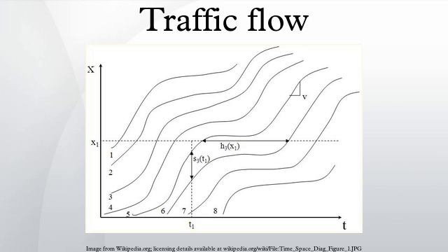Laval 2009 presents a framework for estimating analytical expressions for the capacity reductions caused by a subset of vehicles forced to slow down at horizontal-vertical curves on a multi-lane freeway. In each lane, the underperforming stream is described in terms of its desired speed distribution and is modeled as per Newell's kinematic wave theory for moving bottlenecks. Lane changing in the presence of trucks can lead to a positive or negative impact on capacity. If the target lane is empty, then the lane changing increases capacity.